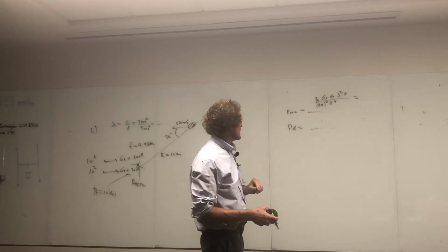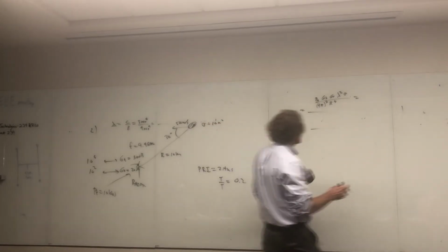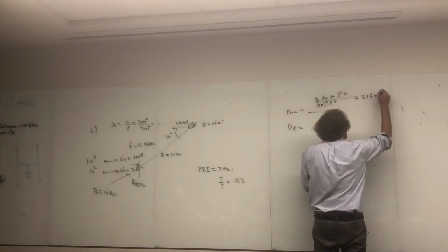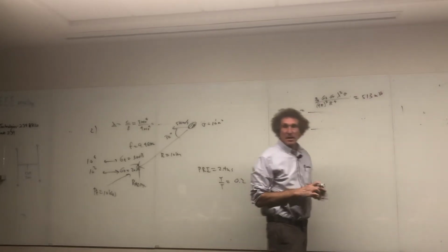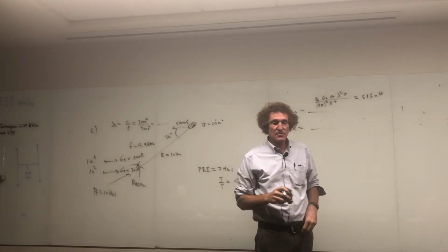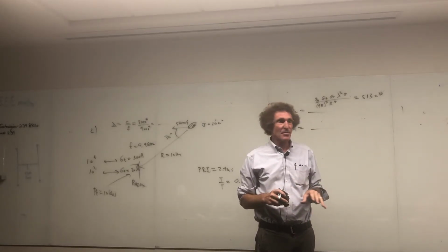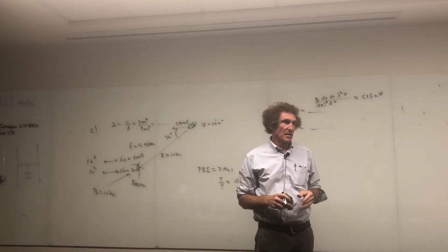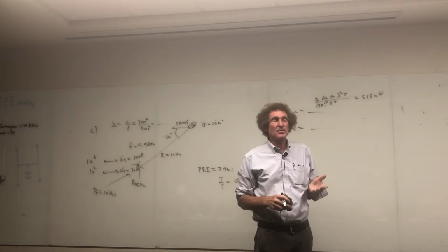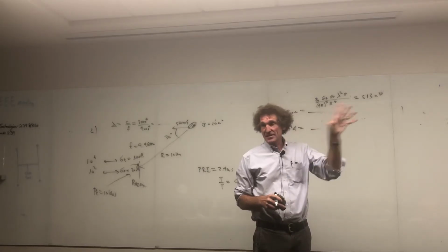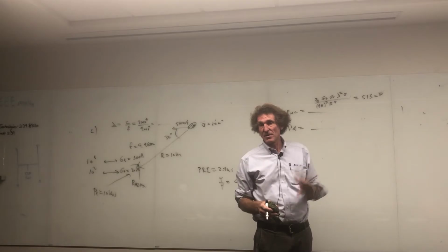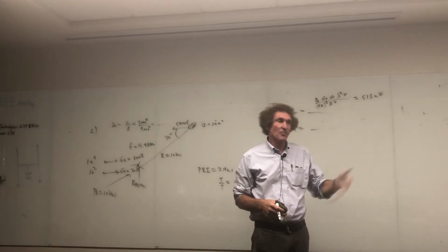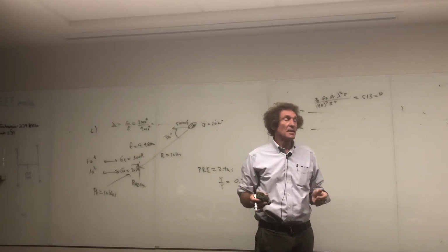When you punch that in, what do you get for this power received? I got 513 milliwatts. Anybody confirm that? If you have your calculators, or if you are using Mathcad, and I'm encouraging that, or whatever you use, Python? Whatever you use, I like to set up systems of equations and just change variables. I don't like to keep punching in equations like this radar range equation over and over again. It doesn't help me.